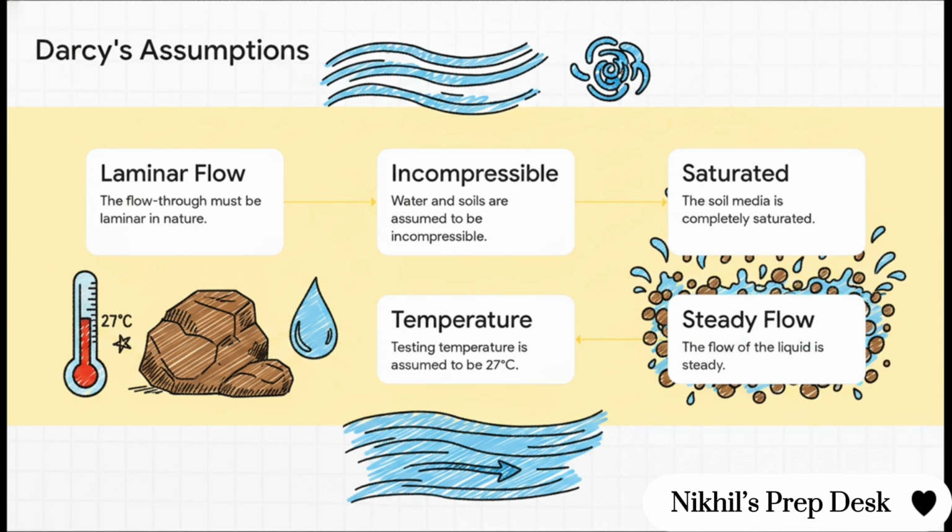1. The flow has to be laminar, so smooth, not turbulent. 2. Water and soil are treated as completely incompressible. 3. The soil must be fully saturated. 4. The liquid flow has to be steady. And 5. Standard testing temperature is assumed to be a nice 27 degrees Celsius.